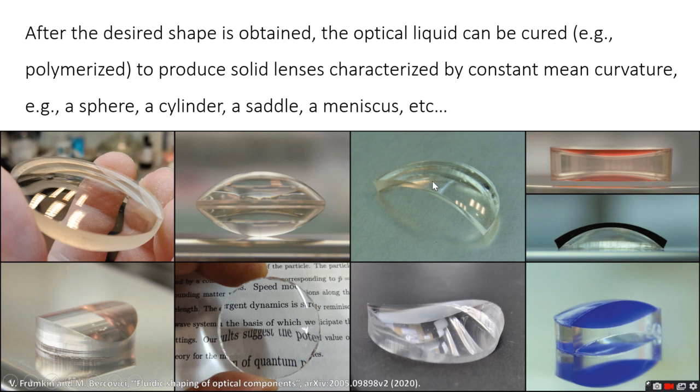In the bottom row, you can see some examples of more complicated lenses, made by the same method. The first is a cylindrical lens, which is created using a specially designed bounding frame. Next is a bifocal lens. This one is created via a two-step process, where a plano-convex lens was first made, then cut in half, and used as part of a bounding frame for another plano-convex lens with a different curvature. Here you can see a saddle lens, also known as a toroidal lens, which has negative curvature along one axis and positive curvature along the perpendicular axis.